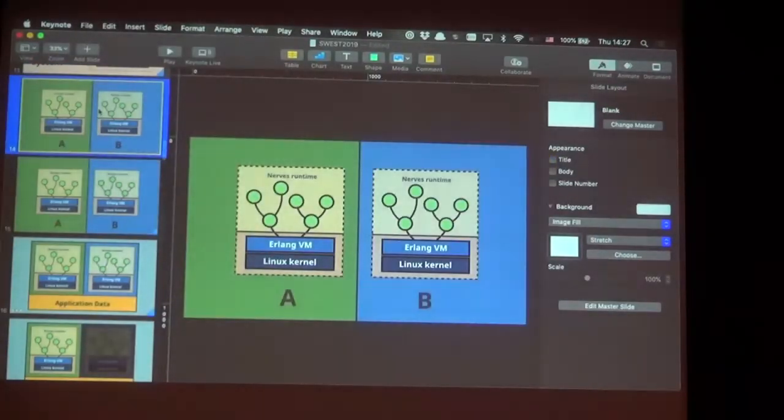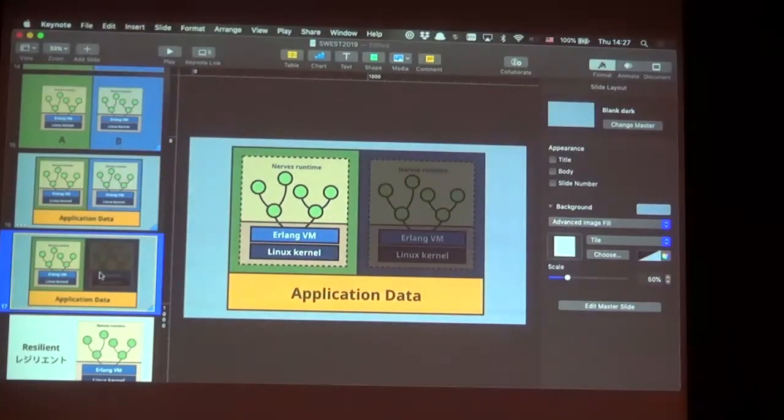You want to know about your slide for resiliency. Your drawing looks like two machines. Do you mean there are different OSes on the one chip or something like that? So this is all on the same device, and what this is showing is this is currently active and running. That's what you're booted off of. And then when a new firmware comes in, it goes into here, and you try to boot off of that. And so there's always a known good working copy to fail back to.